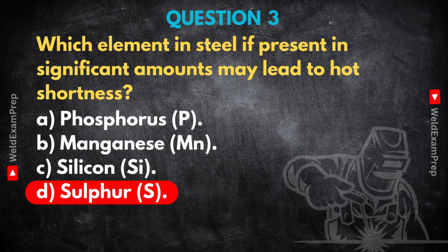So it's a balancing act then. Control the sulfur, make sure there's enough manganese. Exactly. Steel specifications always limit sulfur content for this reason, and they ensure sufficient manganese is present. It's a great example of how metallurgists manipulate chemistry on a tiny scale to prevent major problems during fabrication and ensure the material behaves as expected, especially under the intense heat of welding. But yes, too much sulfur can still overwhelm the manganese effect.